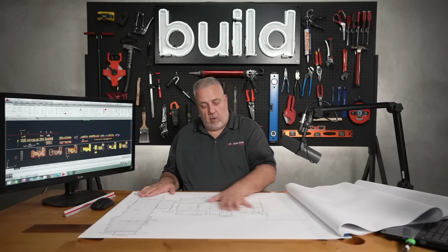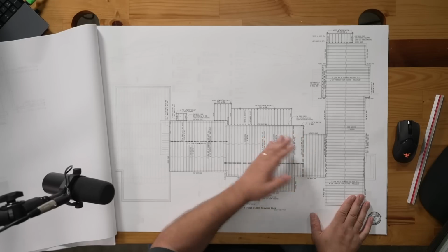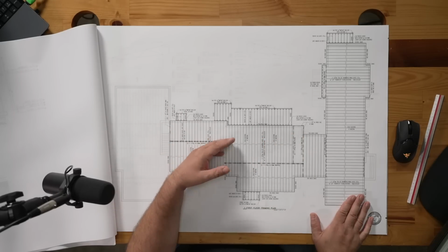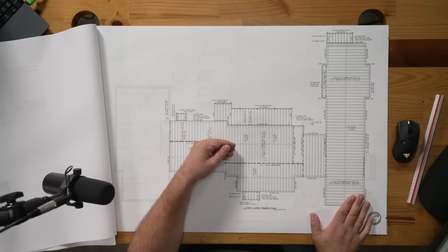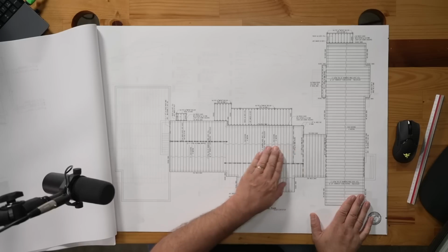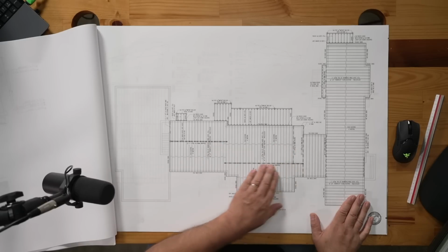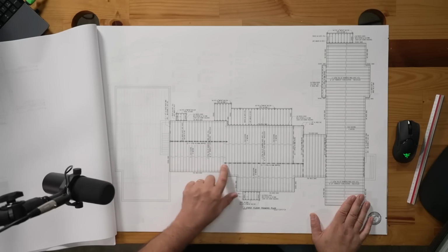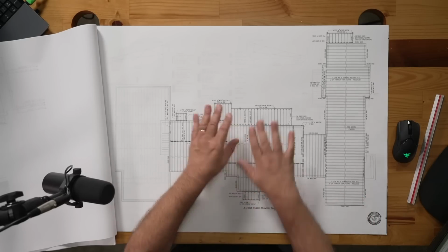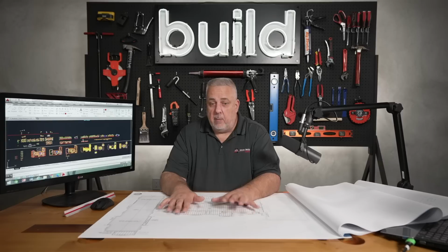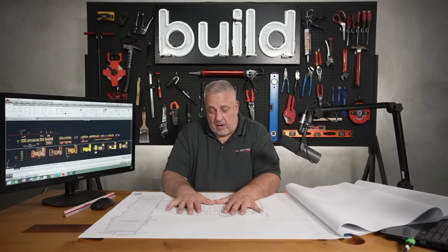All right. Floor framing plan. Again, sometimes you just see these as simple lines. I like to draw out the thickness of every floor joist. I like to draw all the solid blocking. I like to put the beams in. I like to put the column locations in. I like a fully coordinated set because, like I said, they don't leave my office until I understand how to put the whole house together.